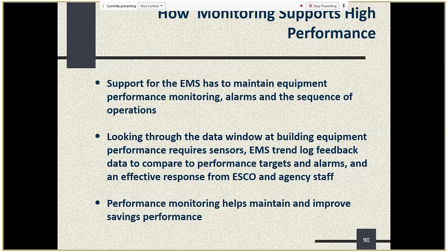What's really important with an EMS system, when that's an integral part of your monitoring strategy, is that you maintain it and support it so that you don't get buried in what I call nuisance alarms, and that the sequence of operations is maintained to achieve the optimization of savings over time.